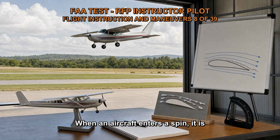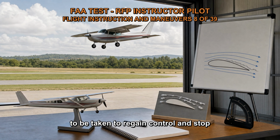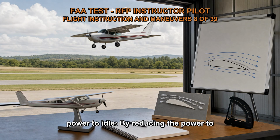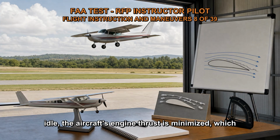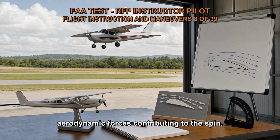When an aircraft enters a spin, it is in an aggravated stall condition with one wing more deeply stalled than the other. To recover from a spin, specific actions need to be taken to regain control and stop the spinning motion. Here's a breakdown of the steps involved. Reduce power to idle. By reducing the power to idle, the aircraft's engine thrust is minimized, which helps in reducing the spinning tendency and overall aerodynamic forces contributing to the spin.